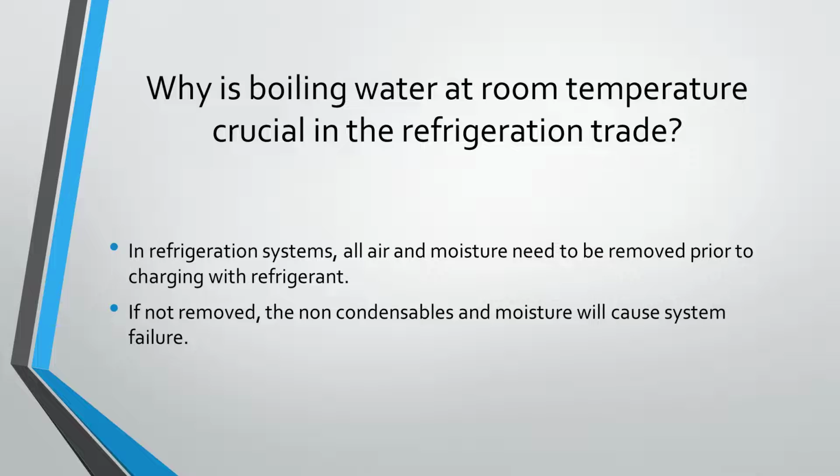Why is boiling water at room temperature crucial in the refrigeration trade? In refrigeration systems, all air and moisture needs to be removed prior to charging with refrigerant. If not removed, the non-condensables and moisture will cause system failure.